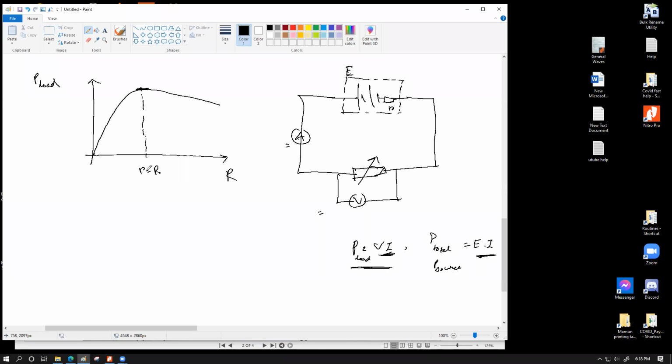And another thing is the additional part to this, which is on the shaded part of the syllabus. Here this is a graph of capital R, which means here the load resistance is 0. So slowly we're increasing the load resistance. At this point, the load resistance became equal to the internal resistance, and then the load resistance got bigger than the internal resistance, which means for this much segment, this is true. And for this much segment,